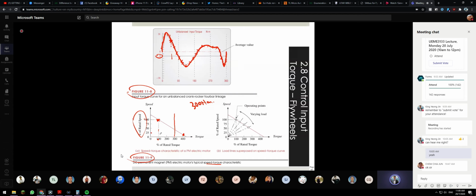So when you choose motors, you have to know what your required motor speed is and what your required torque is at that speed. Then you have to find it from the graph. You cannot go purely by the rated torque and the rated speed.